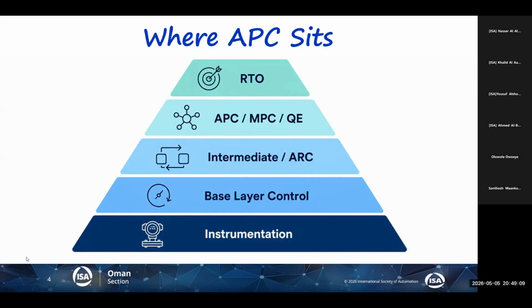A good example is the anti-surge controller, multiple inputs, but one output. One output, one actuator, one valve. So that's still based on feedback. Even here at this level, it's based on feedback, the error. You heard that yesterday.